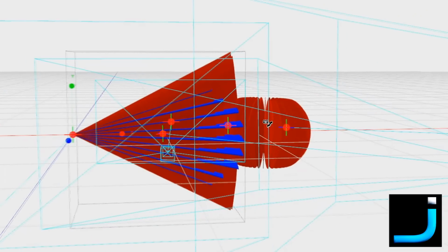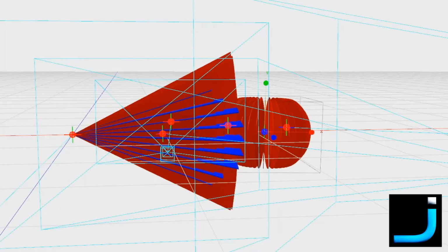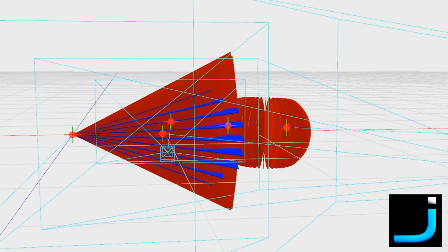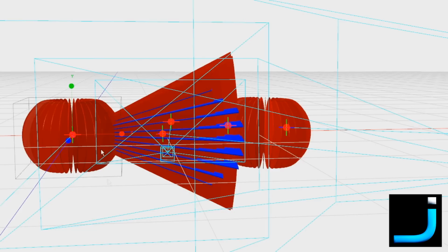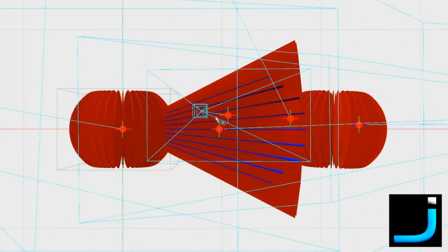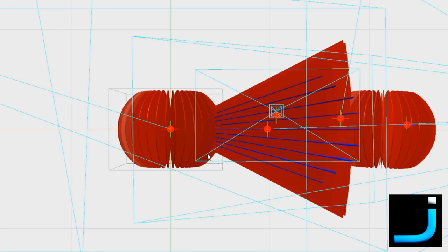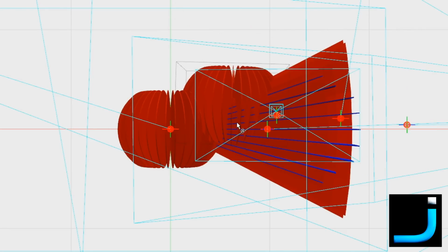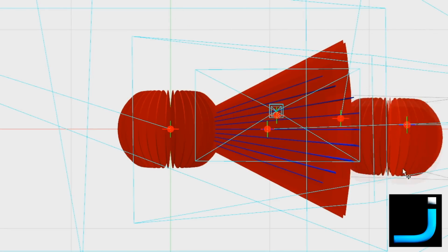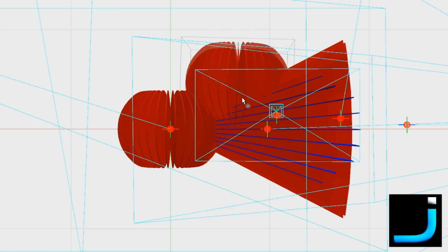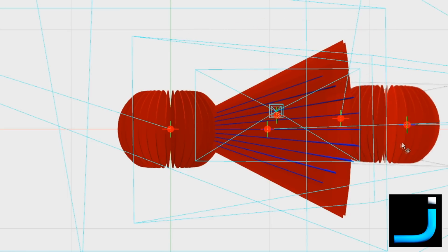What you'll also notice, of course, if we turn on and compare the ground-based rubber ducky pattern, is the range, look. We'll just switch back to the side view. So this is where you're going to get to with your rubber ducky. However, with a diversity receiver, because it's a higher gain, 11 decibel, versus 2 decibel of the rubber ducky, we can get right the way out here.